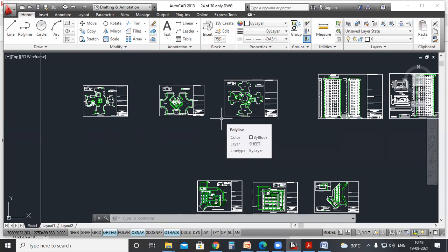Okay, this lightning protection earthing system may be interconnected to the normal earthing that we provide based on the HT set calculation, but it is better to island it, or not to connect all this earthing to the normal earthing system, like the separate lightning arrestor can be provided separately. Okay, no need to interconnect, but you can interconnect if you want. You can interconnect, not an issue. Thus, you can reduce the overall grid resistance. Okay, so I hope it is clear.